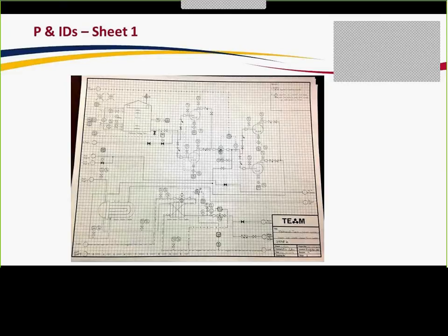So the next thing we looked at was our control schemes. We drew process instrumentation diagrams for each one, and I'm just going to talk about a couple of important aspects of that. We used a cascade loop for most of our control systems, where we had a control valve with a flow controller. Right here for sheet 1, we have the methanol storage tank. The low level indicator controller will cause the pumps to automatically shut off. This interlock system will help not starve the pumps.